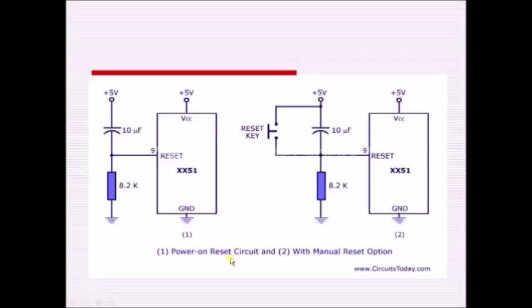For example, assume that we are working on the controller and we want to reset the controller in the middle of some application. So if you connect this supply and if you remove the supply, and again connect the supply, then the controller gets reset. But this is not required for us, so that is why we are going with a switch.